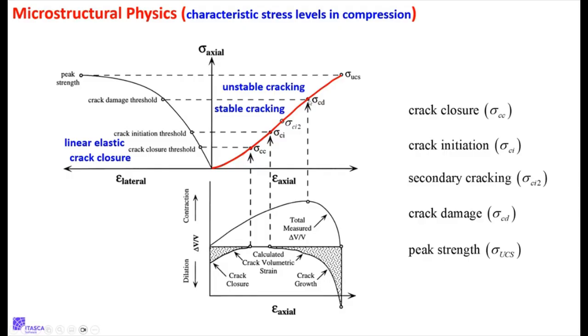Okay. Then you get this point here, which we call crack damage. What does that mean? This means that there's some serious bad stuff happening now. There's really significant damage starting to happen. In fact, it's so significant that the stress strain curve is even bending over. Look, it's not linear. It's getting softening. Right here, the curve got steeper because it was getting stiffer, because there were new surfaces in contact. Here, it's busting apart inside so much, it's not carrying as much load.